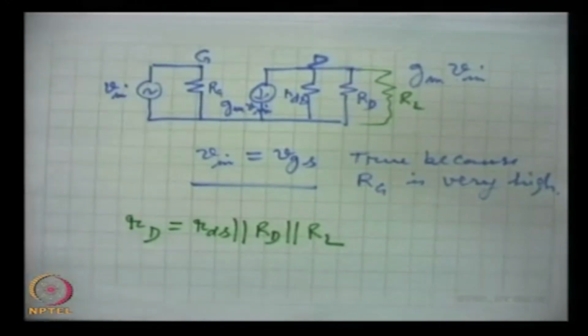One thing very frequently used in electronic circuits: when two resistances, one high and one low, are connected in parallel, the effective resistance of the combination is smaller than the smaller resistance. Take just one example, 100K and 1K in parallel.